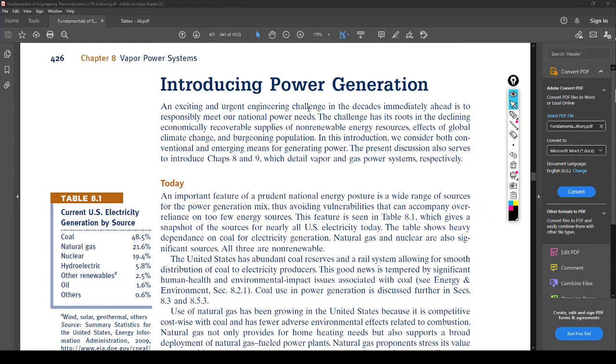Now, this is a basic power cycle, by the way. These are the basic ideas, but there are other variations of this that have a lot of other parts in them. But this is the basic one, where we run it through the condenser so that it loses all of its heat to the environment, and so now we're just at water, right? We just want saturated liquid.